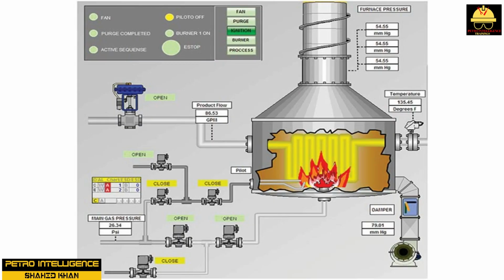Fuel system. Located under or on the side of the furnace is a complex network of lines that provides fuel gas and air to the burners. The fuel is stored in a tank located a safe distance from the furnace. In an oil burning system, atomizing steam and an oil preheating system are added to the network of pipes. Most injuries encountered in furnace operation occurred during startup of the fuel burning system.